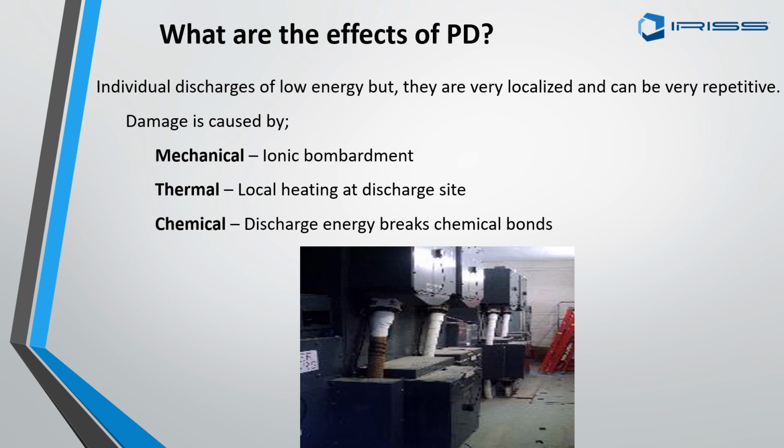So the actual arcing can slowly eat away at the surrounding insulating material, making the gap internally larger. That defect gets bigger over time, but it also changes the surrounding material's chemical makeup because of the combined heat and electrical energy that's being discharged. It can have a breakdown effect chemically on the surrounding material. So it can slowly release gases, it can slowly carbonize, it can do all kinds of things depending on how it reacts in the presence of a little spark.